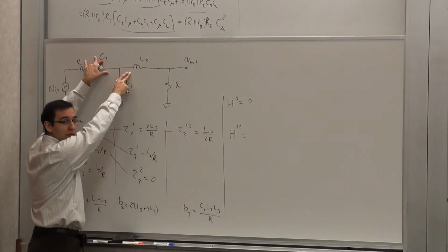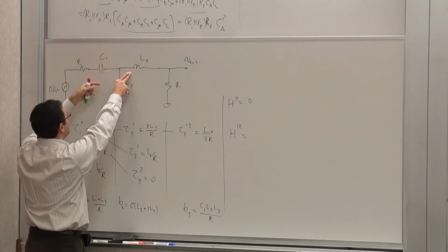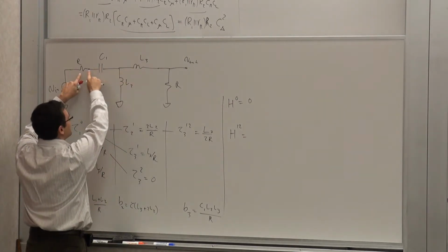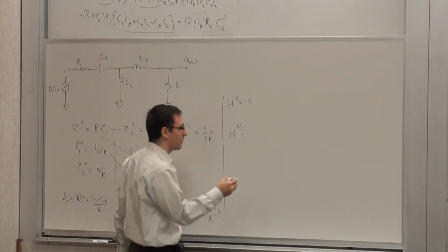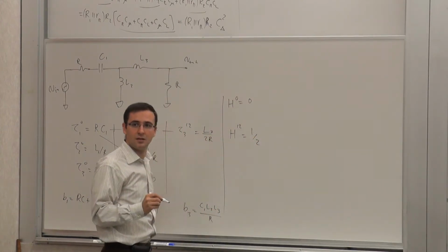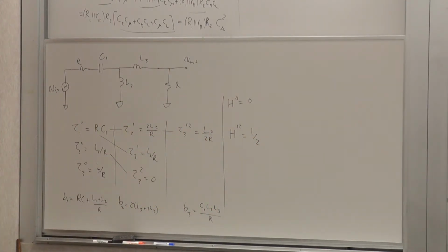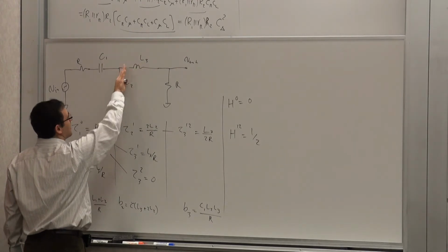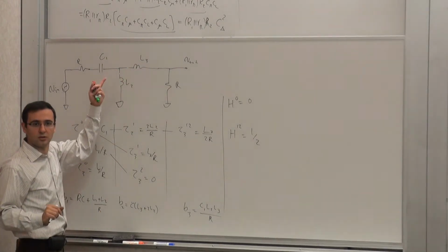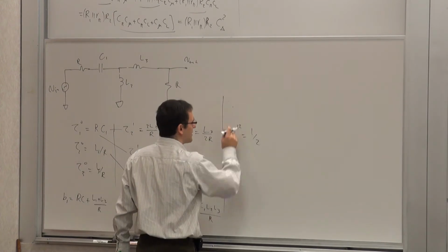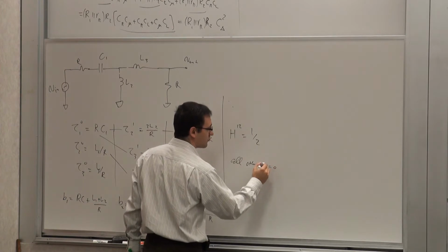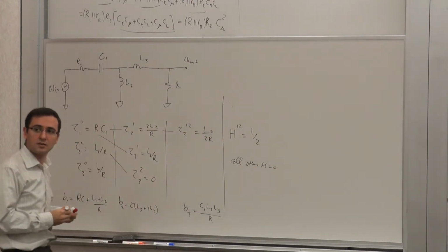this is open, this is shorted. And what is the gain? What is the transfer constant? And this is shorted. This is shorted. This is open. This is short. So this is basically resistive divided between two resistors of equal value. That's 1/2. Anything else that would do that? If all three of them are infinite value, this is infinite value, this is infinite value, then nothing gets down, and this may be shorted. So this is the only non-zero one. You can say all other transfer constants are 0.